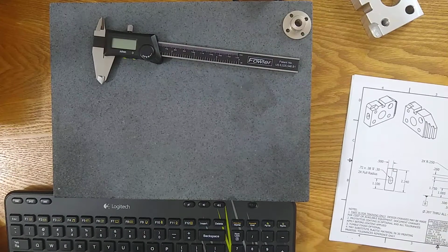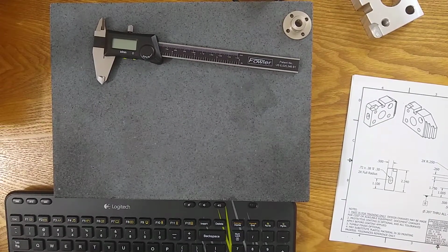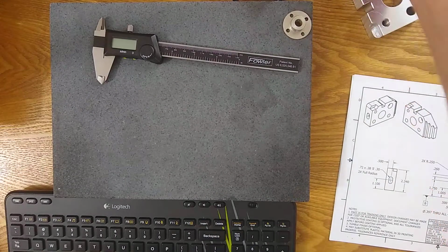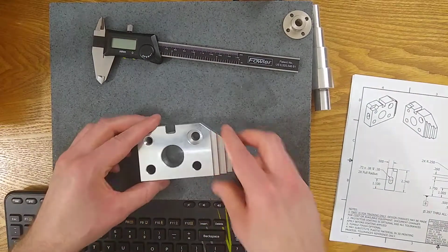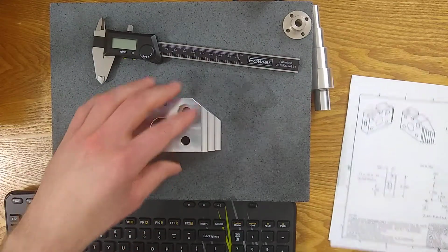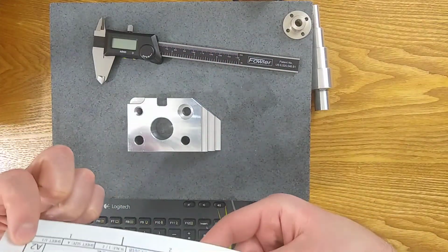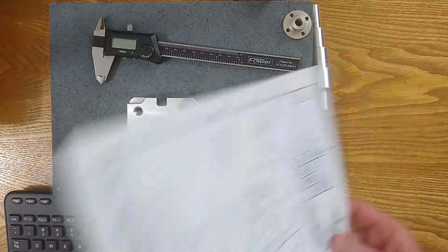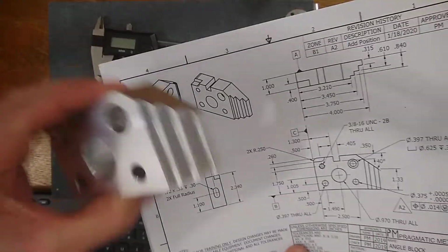So let's continue with section number 4 of this video, the important steps. If you've watched the other blueprint videos so far, you'll know I've emphasized certain things. First thing, when you get a part, you're going to inspect this part, or maybe you're going to make that part. Grab your blueprint and verify the part number, PM-02, revision A2. Verify that against your traveler, your print. Make sure the physical part matches.